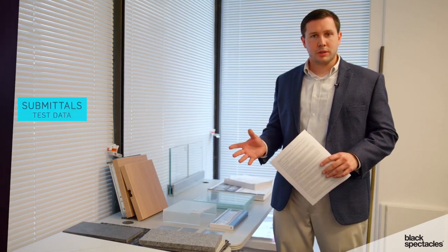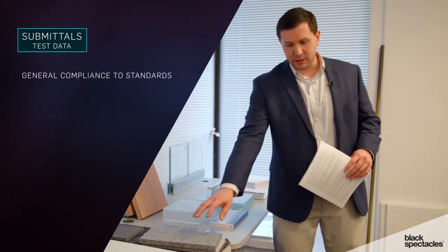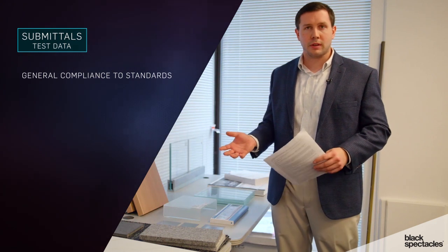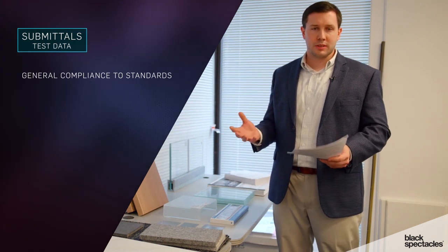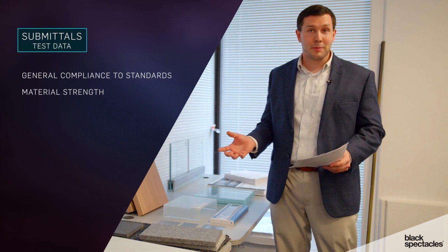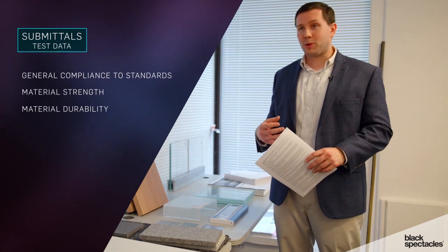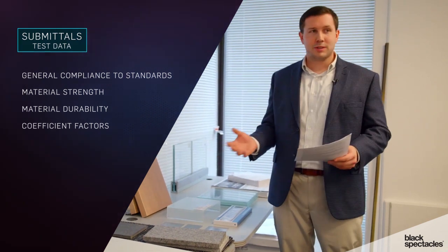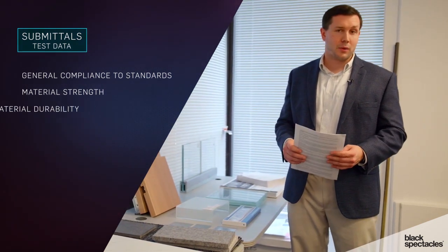Peachtree Center project. Another important part of evaluating the contract documents versus the work in place is going through the submittals. As I mentioned earlier, there are a lot of different submittal types. The first one's probably test data, which is general compliance for each material based off of, say, ASTM standards or specific trade organization standards. This is making sure that the material itself is strong enough, a lot of times durable enough, has appropriate factors, say for slip coefficients, has appropriate noise reduction coefficients. There's a myriad of different things depending on the product.